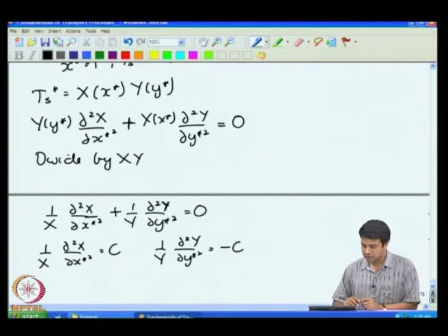Okay. So, briefly in this lecture we started off determining a general differential equation for transport in Cartesian coordinates. The fundamental principle: the rate of change, the amount of concentration increase or decrease within a differential volume has got to be equal to the sum of what comes in, what goes out, as well as any production within that volume. The change within that volume is equal to the change in concentration times the volume, and what comes in is due to two reasons. One is due to diffusion, the flux, the other is due to convection.